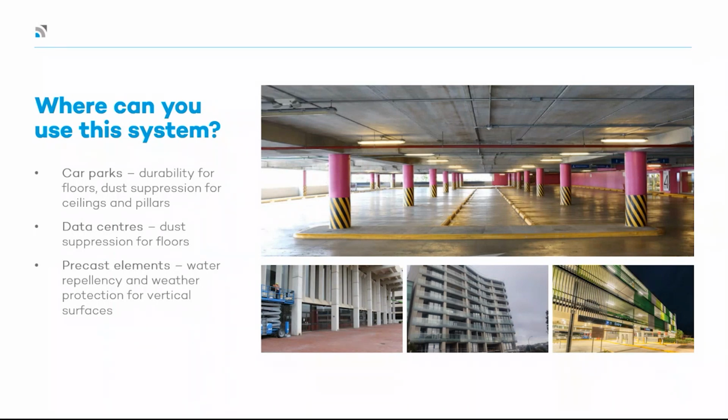Precast elements are another way that the construction industry is moving forward. So being able to treat those precast elements prior to them going to site, and knowing that once they're treated, it's a long-term solution. So having that deep penetration of 150 mil. Now, I'd like to mention that that penetration is actually 360 degrees. So you get the same depth of penetration in a soffit that you would in a slab on ground, because you're not relying on gravity to get into those. So yeah, as I said, precast elements, being able to treat them for things like water repellency, weather, chloride contaminant ingress through that facade is definitely a way forward that this INFRA-TECT system is looking to assist the construction industry.